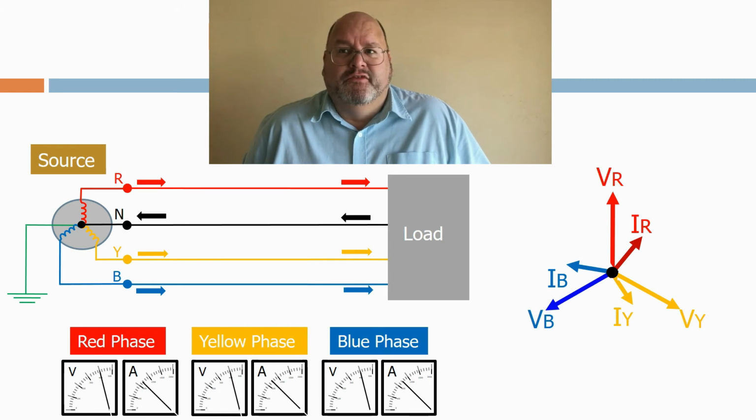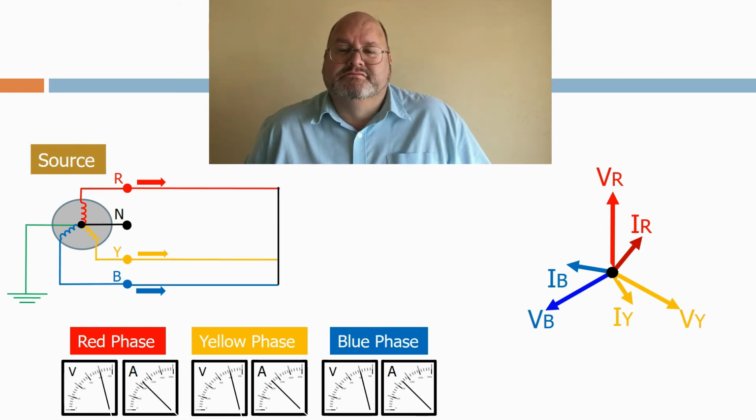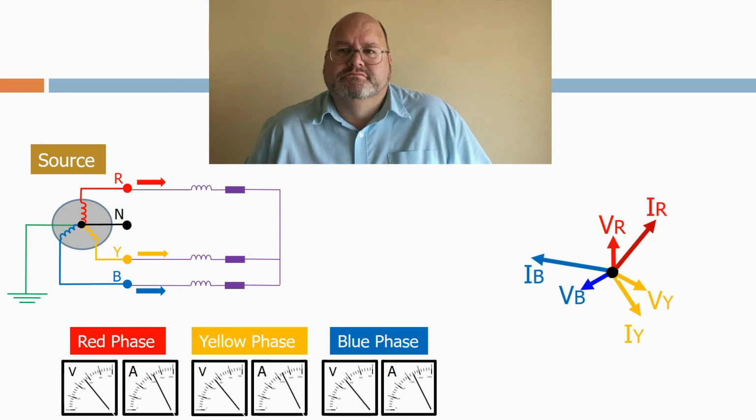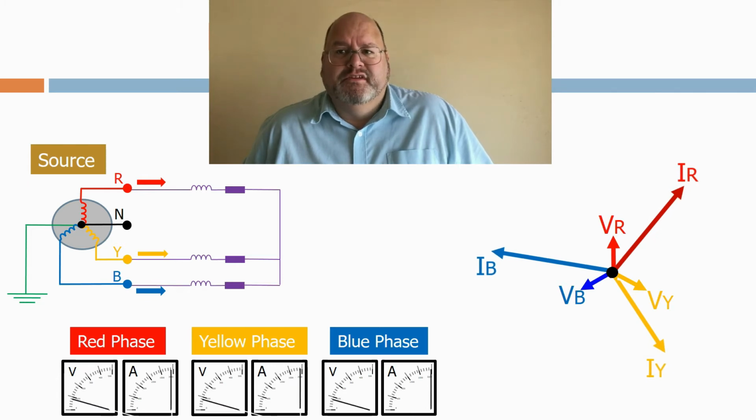Finally, let's now look at a full short circuit across all three phases. The impedance of the faulted circuit now represents a balanced fault, consisting of only the phase conductor impedance on each leg. Let's see what happens to the voltages and currents. As we can see, all three-phase current magnitudes increase significantly and flow equally between the three phases. We now have line currents instead of phase currents. All three-phase voltages will now reduce substantially, but they will remain in phase as the voltage is balanced.